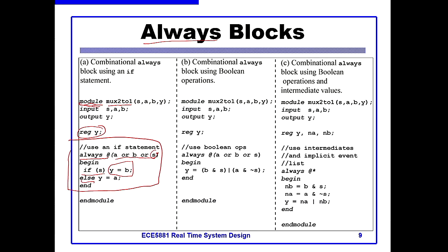Okay, so we can do this in different ways. You'll see this is the preferred way on the left, which is the higher level manner. But within an always block, we can also generate Boolean expressions if we want to do that. So that's what you see here. It's a very similar syntax to the assign statement, except you'll note there's no keyword assign in front of that symbol. And the other question I often get is, why have you got this begin end here in the always block?